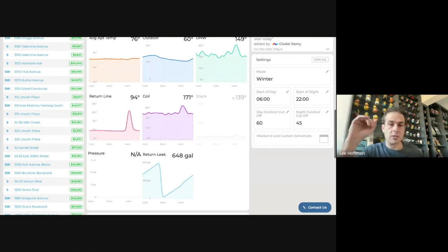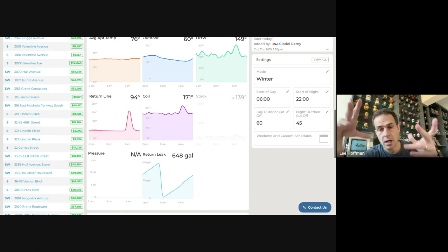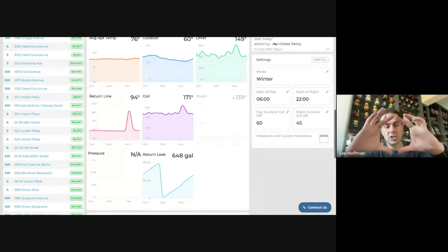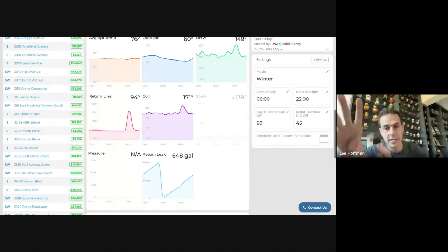And what you have to use is what's called an infrared gun. A lot of boiler service companies have these, so they can usually do it. There are also companies that specialize in this. What it does is it looks for heat underground. It does thermal mapping. They'll aim it at the ground and look for spots where there's like a pool of heat, which indicates that there's hot water underground.